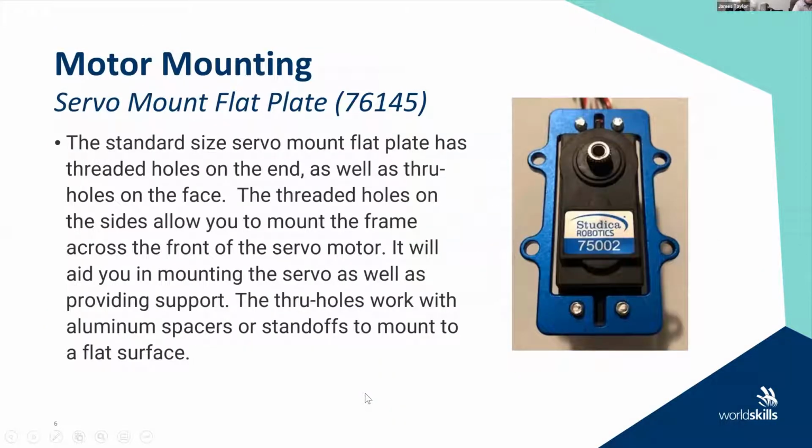All right. There are benefits and disadvantages to both. I actually had them in the presentation, and I did take them apart. Some can be more sturdy than others. We can do some that are faster. Some will have a little bit more accuracy. The rack and pinion that I had up was fairly sturdy, but if you get them too big and they're not tight, there can be a little play in the rack and pinion, and that's just because in the gear system there's going to be a little play as you go forward.